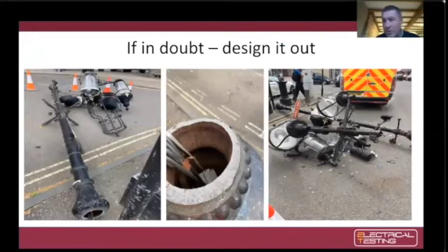Because you never know. You can have a column that could be substantial in appearance. It might be a column that you haven't had problems with over a period of time, but that fatigue can set in due to weather conditions, and parts of the column can deteriorate and may not be subjected to non-destructive testing. And where you've got a configuration of multiple lanterns or floodlights or anything excessive, then the potential for failure is there. So if in doubt, remember to design it out.